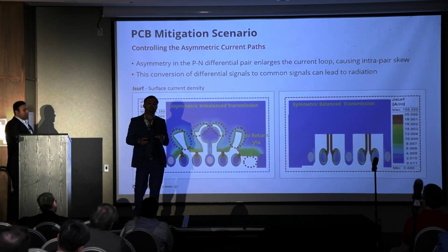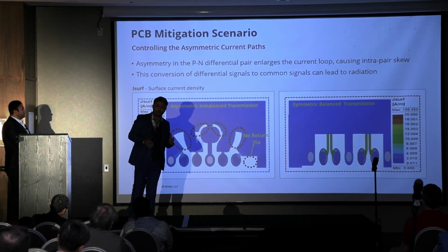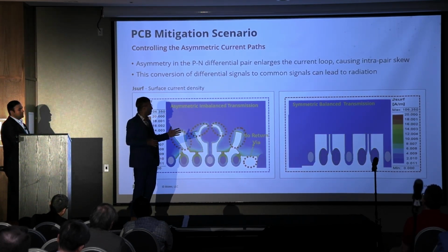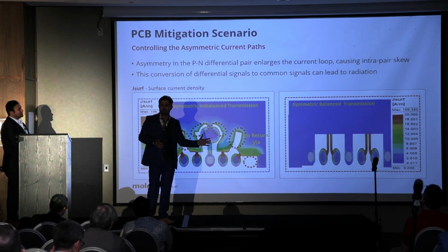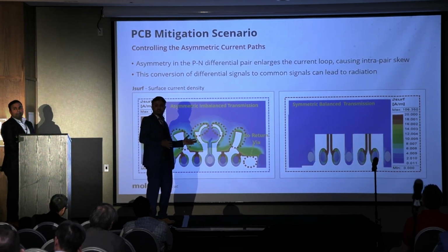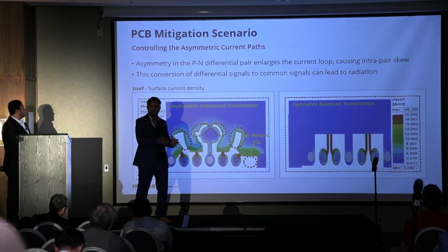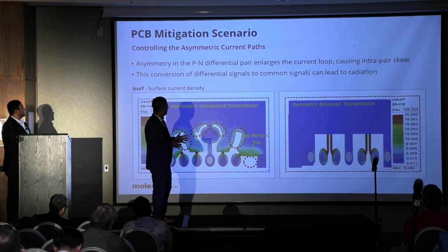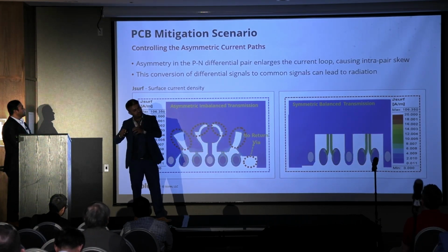In that differential pair, two kinds of signal can propagate. One is a differential signal that sees a differential impedance as it propagates down the line, and another is a common signal that propagates seeing a common impedance, right? Now in any practical circuit, both signals propagate.